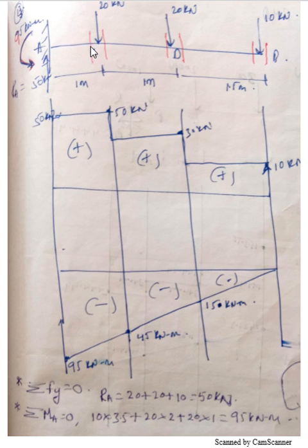Okay, so that is why if you come from opposite end, the calculation is going to be easy because we are not going to consider this reaction moment. Alright, so first calculation is to calculate the reaction force. For that I am going to consider summation of Fy equal to 0. There is only one upward force which I am going to take as positive. So upward force is positive Ra and rest of the forces are downward. So those will be minus 20 and minus 10 equal to 0.